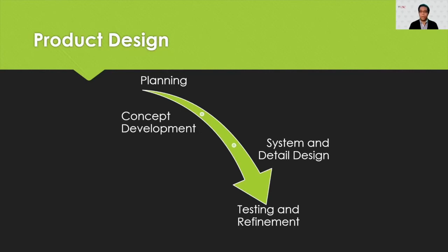First, we need to identify the needs of the people who will use it. Then we brainstorm possible configurations that will solve those needs, including the physical properties of our product, what materials we will use, and how we will manufacture it. Then we refine our design with the known limitations and constraints, and we develop prototypes, test them, and modify everything that needs improvement until we have a finished product.